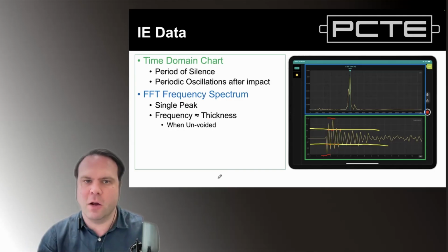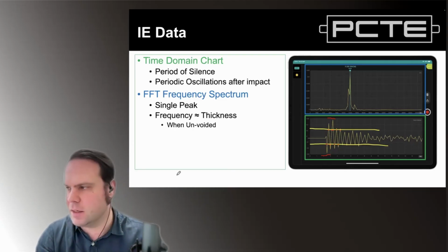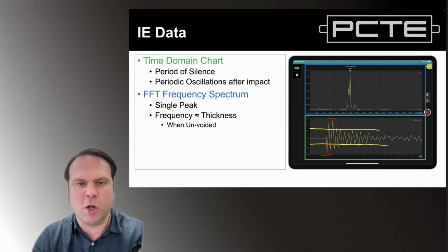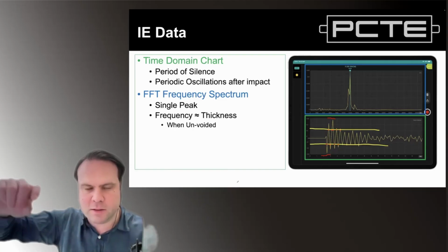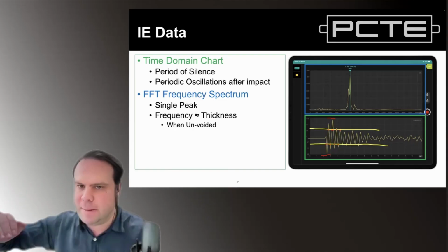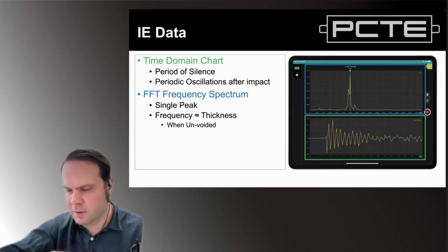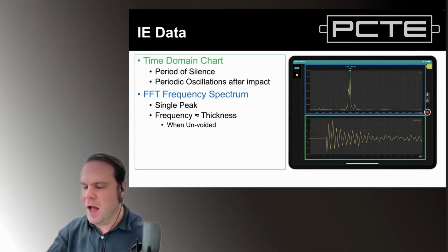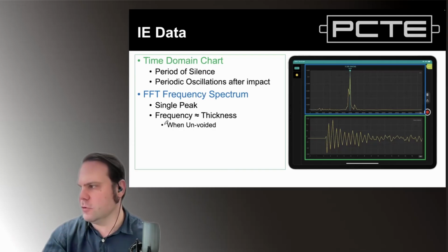So first sign of a good time domain, a sound wave chart, is we don't go above or below the top of the chart, and our repeating frequency peaks don't flatten off, go clipped by the influence of too much gain, along with a period of silence followed by the signal arriving.